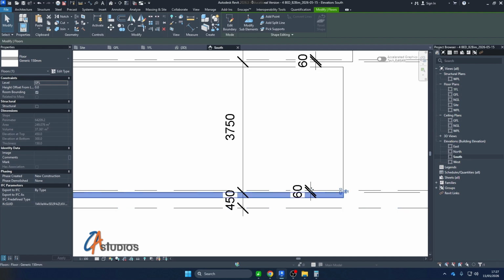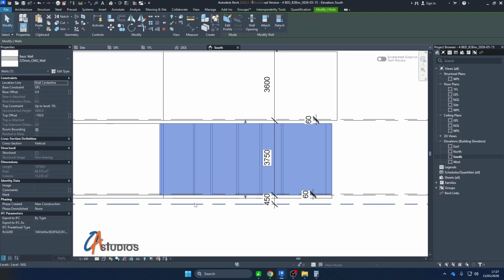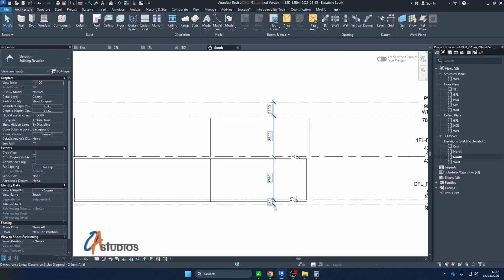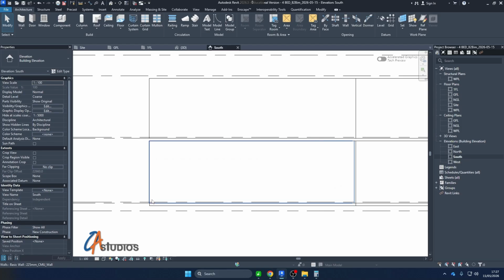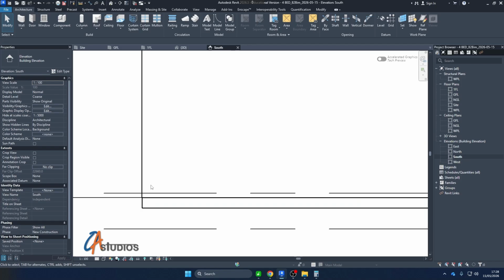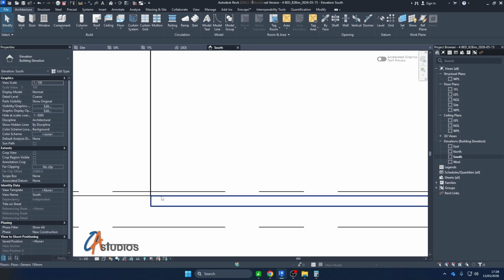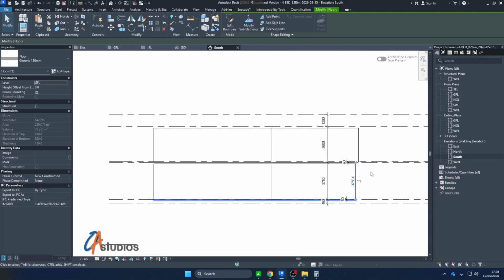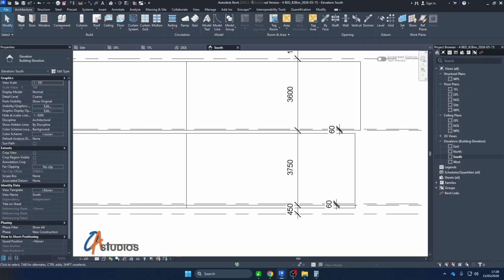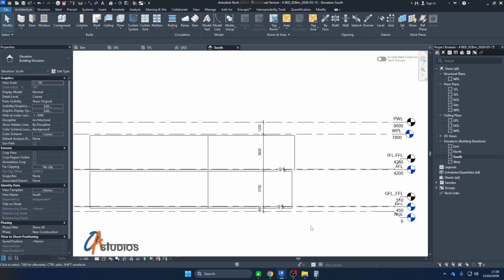so that I don't have to put the foundation walls there, since I'm not doing any serious coordination or documentation. But if I was going to use the information generated from this model for maybe costing or creating schedules, I would leave this at 150, because that's what it's going to be in the actual sense, and then add the walls from the foundation that are going to be here.